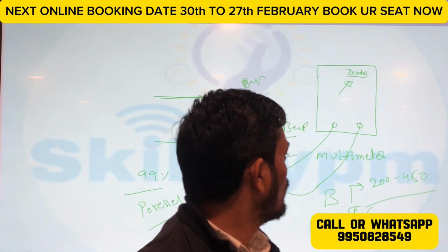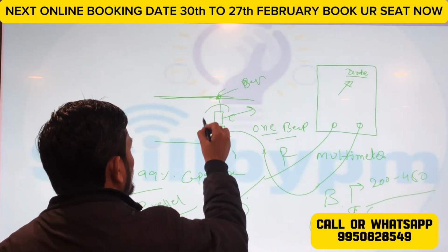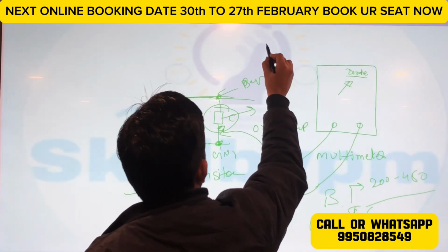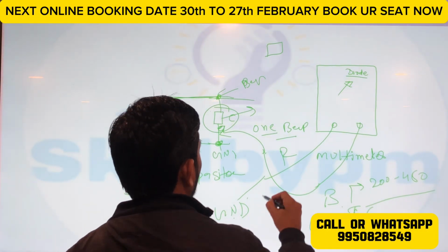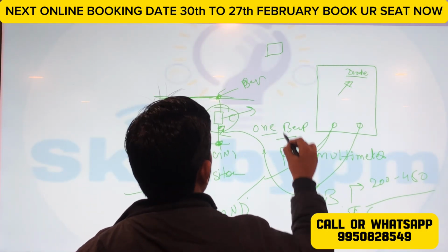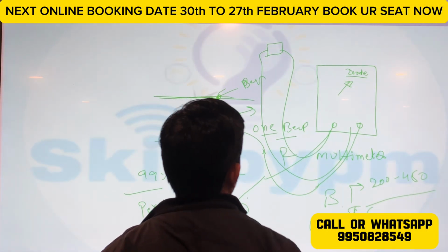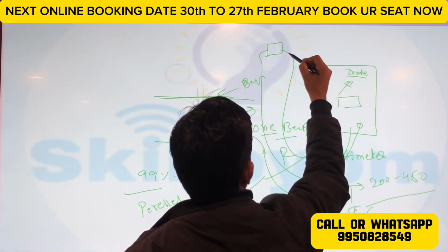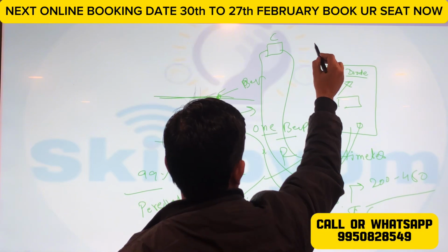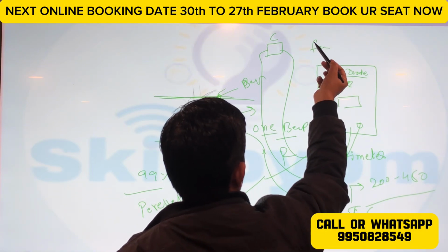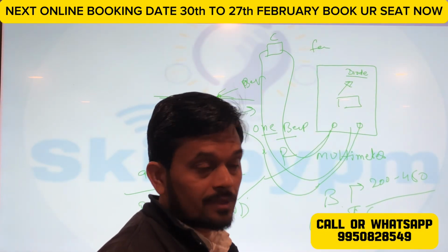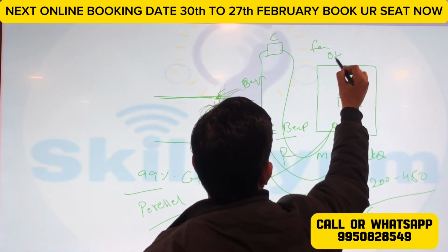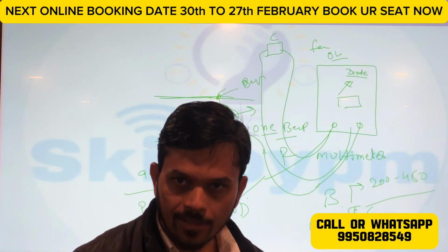Okay. Now we remove this capacitor from the board and we put it here and now we connect both wires on this capacitor. If we find any reading in this multimeter, it means this capacitor is faulty. If we find a beep, it means this capacitor is faulty. And if we find OL, it means this capacitor is okay.